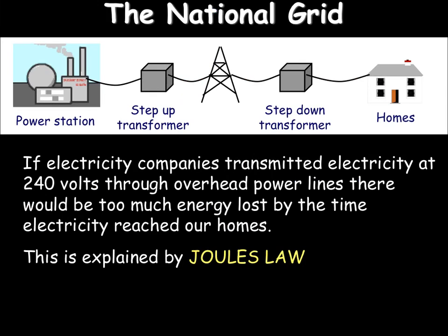Okay, so why even use alternating current? Why not use DC for everything? For most devices, apart from the lights, everything we use uses DC and has to be rectified, changed from AC to DC. The reason is transformers. A power station produces maybe 500 to 600 volts. It's then stepped up to 50,000 volts and then transported at those 50,000 volts till it gets to a step down transformer near your house, where it's slowly stepped down, usually in 2 stages, to 240 volts.